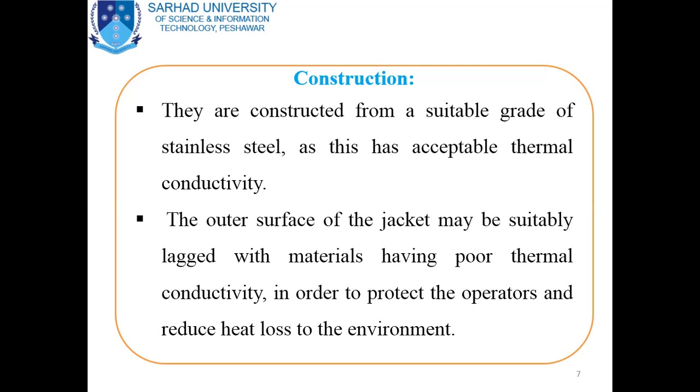The outer surface of the jacket is lagged for that reason: to protect operators and to reduce heat loss to the environment, since thermal energy would otherwise be lost. We are talking about the outer surface of the jacket, which is lagged with materials having poor thermal conductivity, to protect operators and to reduce the thermal energy loss to the environment.